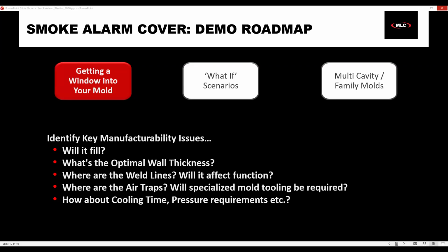This is an iterative thing. It doesn't take a ton of time to run, but it does take a couple of minutes. It's going to go through your geometry and try to give you the optimal location for the injection. Now, in some cases, it might say the optimal location is here, and you're like, yeah, but that's impossible. That does happen.